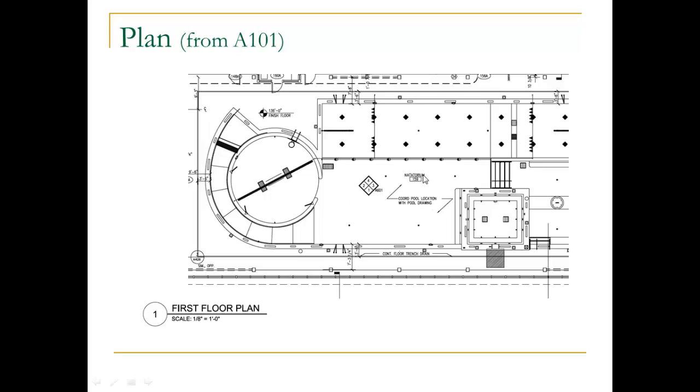This is the natatorium. It's room 159. They give some references, some dimensions. There's some details here. You can see this detail here is on A426, which looks like detail 3. It lists some dimensions from the outside wall. We have a finished floor elevation, 136 feet 0 inches for this finished floor. So we can see that from the floor plan we're referencing other areas of the drawing set with these numbers.